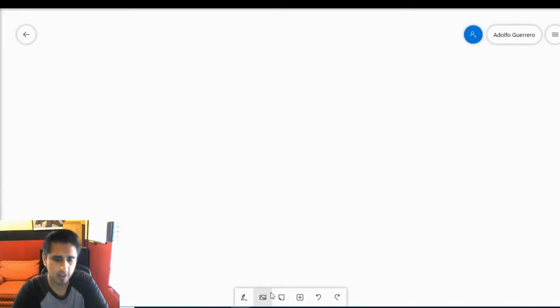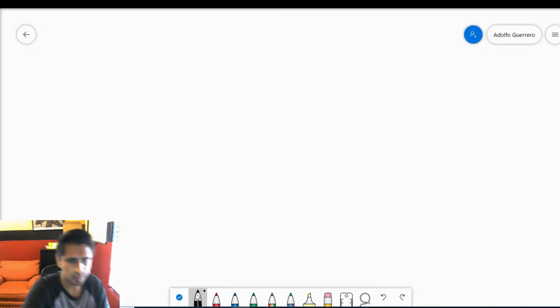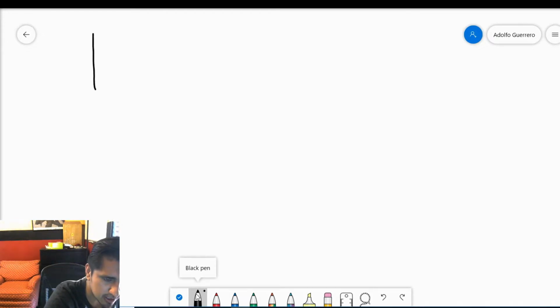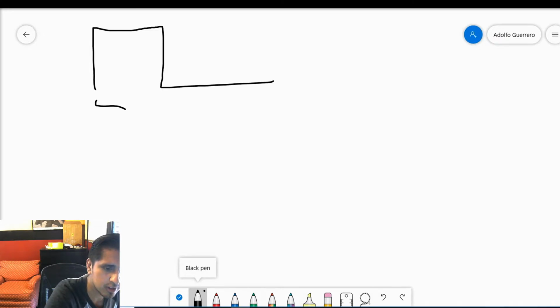Okay, so we're going to talk exactly how we're going to use the microcontrollers in order to generate a trigger signal. What we need to do is generate a signal that looks like this. It goes high, and then it's maintained high for a duration of 10 microseconds. And again, this is according to the data sheet. So this is the trigger signal.